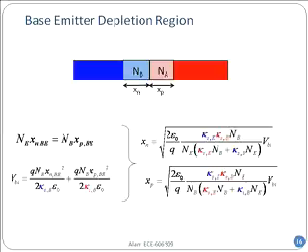One thing you realize, because I have this gain through band gap difference, I'm no longer constrained to having the base doping lower than the emitter doping, because now the emitter doping could be lower than the base doping. In general the gain could then have been less than 1, but because I have this band gap difference that is giving me so much, I can spend it on inverting the doping sequence, right?